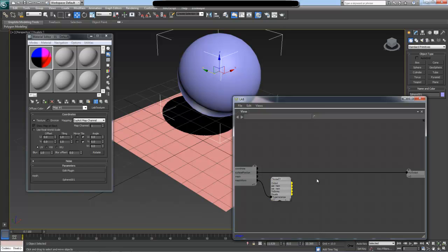So basically we want to multiply. I'm going to add a multiply node, and it's going to be multiply alternative 2, which allows you to multiply transformations by vectors. And as the transformation, I'm going to select the inverse, and this is inverse because originally, remember, we have our object to world coordinate, and the inverse will give us the opposite, the world into object coordinates. And the surface position is in world coordinates, so this will bring it into the sphere's object coordinates.